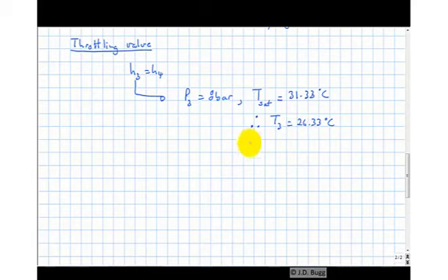So now what we actually need is the enthalpy. Using this temperature, we can get an enthalpy at point 3, and that works out to 86.222 kilojoules per kilogram. And of course that's also equal to H4. Now the way we found this, remember this is now a liquid. So once it's a liquid, we can ignore the pressure, and this H is just the saturated liquid value at this temperature. So that's where this comes from. It's the saturated liquid enthalpy at that temperature. Okay, so that's where we get that.